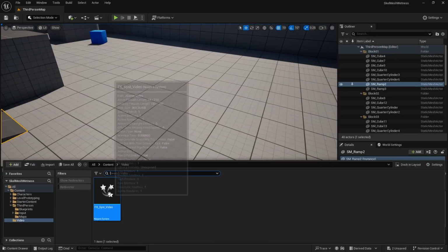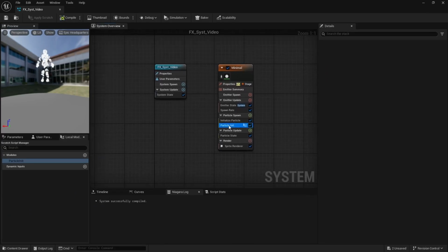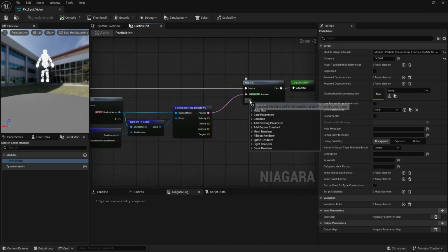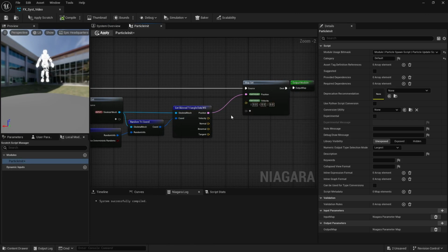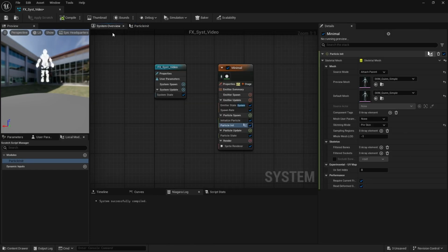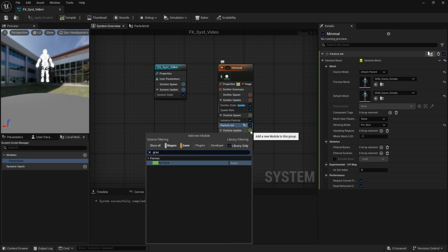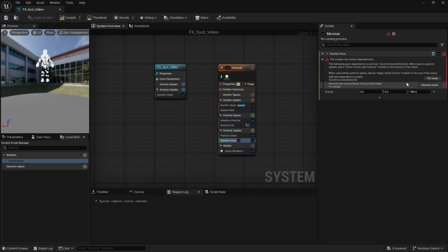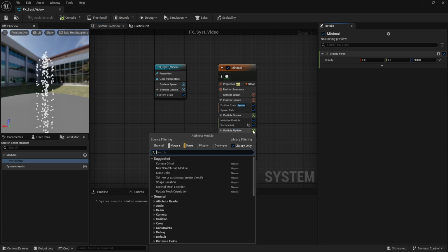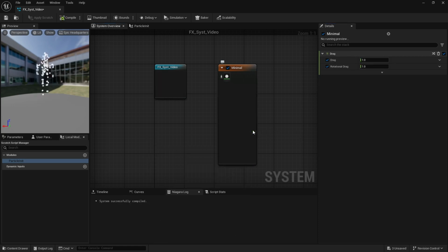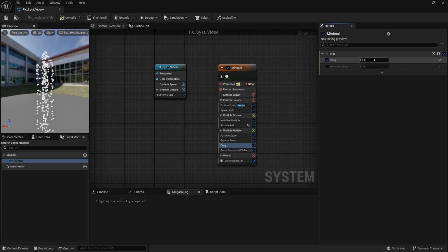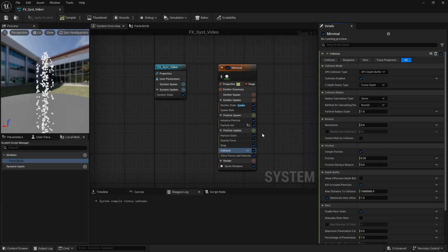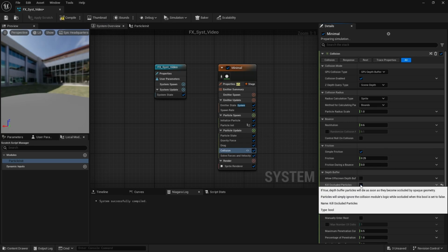Let's take it a step further. Let's set the particle initial velocity. Add a gravity force module. Add the required solve forces module. Then add a drag module. We don't need rotational drag though. And let's use a drag value of 2. Next, maybe a collision module, and let's try turning off the option to kill occluded particles.